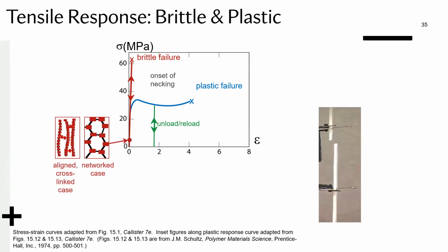What's happening here is that you have a material that's either very crystalline, with a perfect network polymer, or you've got a highly cross-linked one. You remember we compared these different materials, and we saw that if you start from just linear chains, moving towards secondary cross-links, and then towards a more network structure, the strength is always going to increase. And so both the highly cross-linked and the network polymers have brittle failure performance.